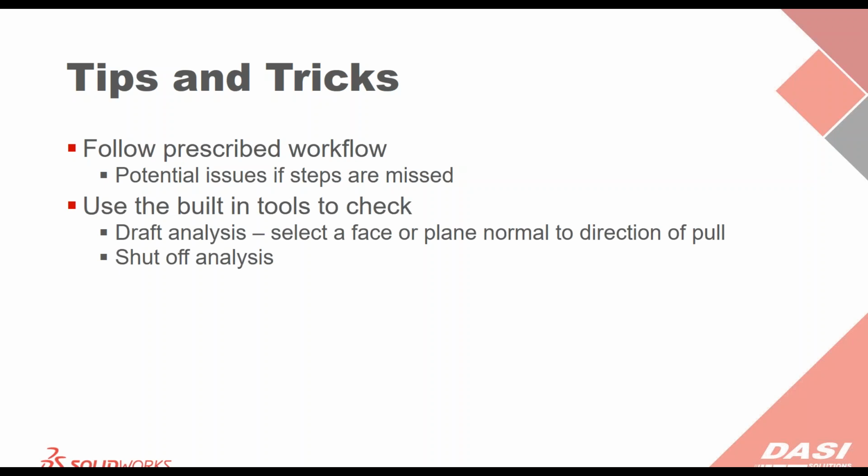There is a lot of forethought and a lot of thinking in mold tool design and how you're actually going to create the parts, create your correct cores, create your shutoffs, and any other geometry that you want to have in there, especially if it gets to be pretty complex. Use the built-in tools to check yourself. So the draft analysis: select your face or a plane normal to the direction of pull, and verify your surfaces are drafted correctly before you move on and start creating your mold. You check the shutoff analysis. If you have very complex parts, you may want to look and see what it's telling you as far as where you need shutoffs.